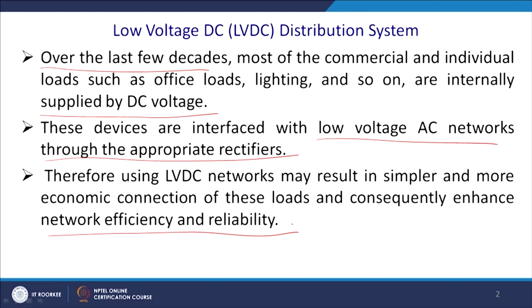Your cable rating, the power handling capability of the cable, is required to be derated, and your transformer is required to be derated. It may also cause interference with the communication network, as well as oscillations in the power system, because you may have a natural frequency of oscillation that is close to the 7th harmonic in most cases. Mostly you have a capacitor bank, and you have the leakage reactance of the big transformer, and that gives you the natural frequency of oscillations.